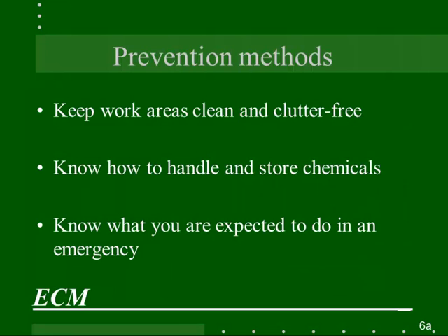All right, so there's been studies done that show that for whatever reason, housekeeping reduces the potential for a fire. So you want to keep your work area clean. You don't want to have, say, dirty rags near chemicals that are still out or a source of ignition. It's just another chance for a fire to start. There's a lot of machine shops in central Jersey, Kenilworth Union area, where they were having fires in the middle of the night. And it was because rags they used to clean these metal parts with solvents were being thrown onto workstations, and that was basically spontaneously combusting in the middle of the night.